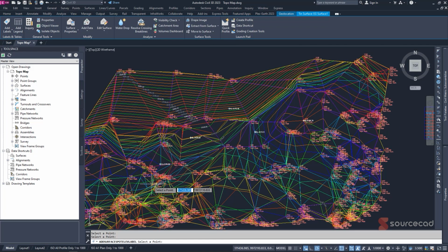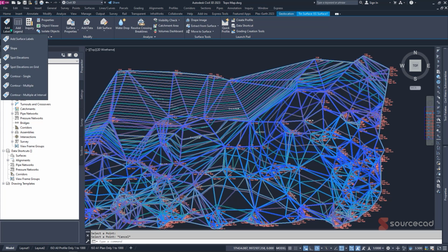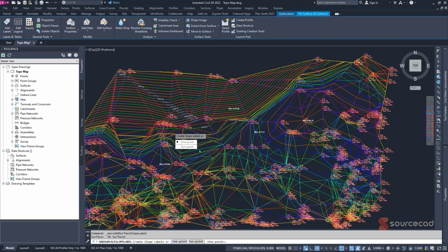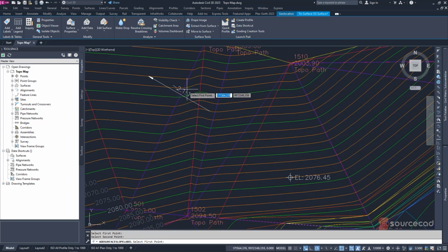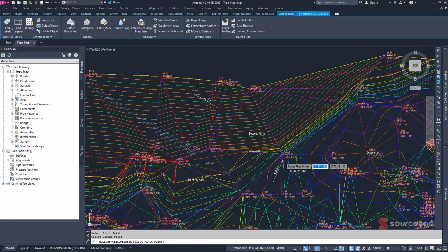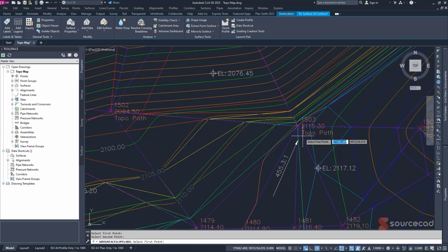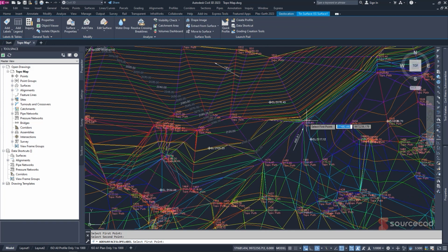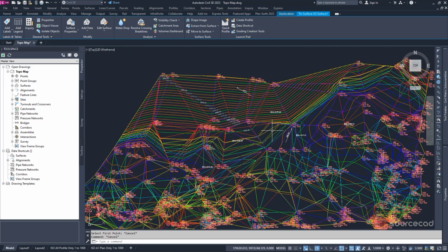Not only that, you can also show your slope so as to understand how maybe the water is flowing. So hit escape and then select that you want to show slope. So select slope. You want maybe 2 points. So you can select your first point here and your second point being there. And the slope at this area is negative 2.1:1, while this slope here is 455.3:1. So that's simply how we show our slope within this area.